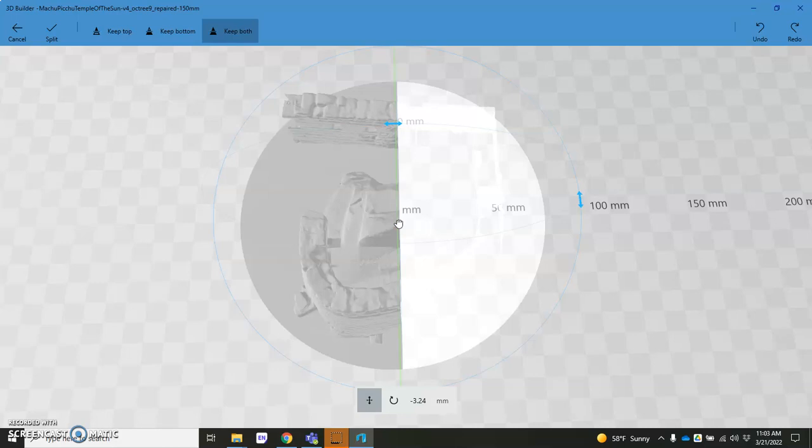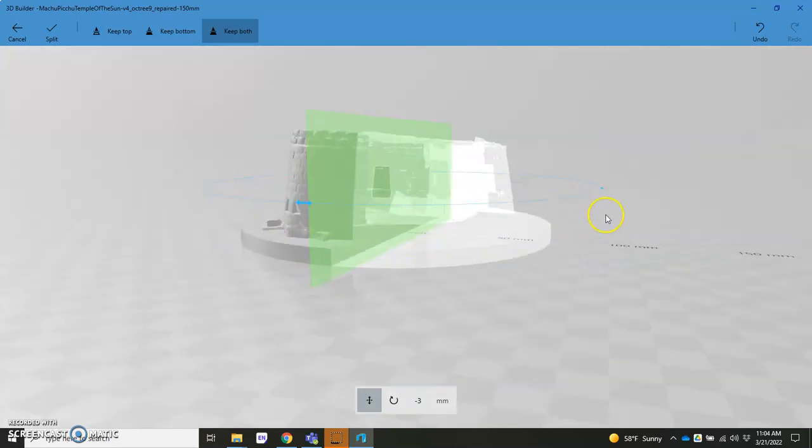I think this is a good center point for me, where I've shifted it negative 2.55 millimeters to the left, right? So it's kind of nice you actually get a readout here. And if you want to be super exact about it, just click down here the button and you can enter your own value. Let's go with -3. Right, now it's shifted just the tiniest bit so that I'm at -3. Let's see if that's where I want it to be.